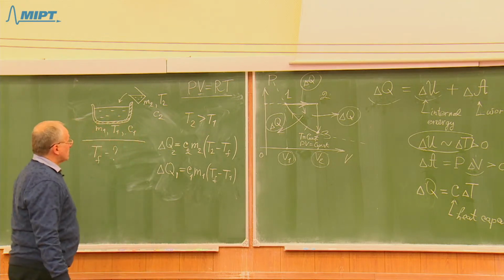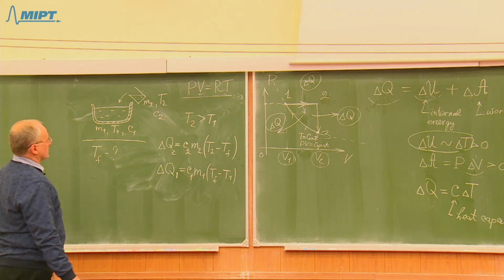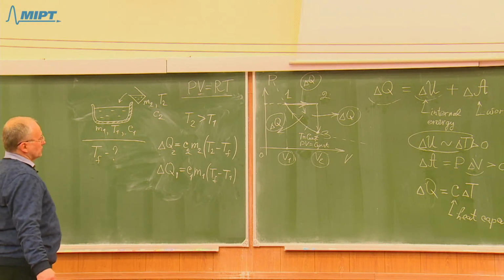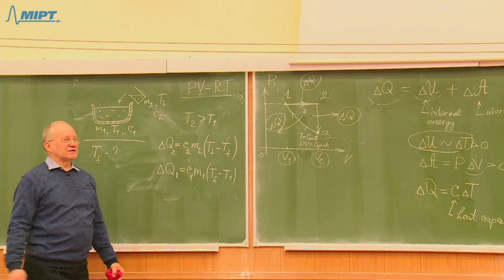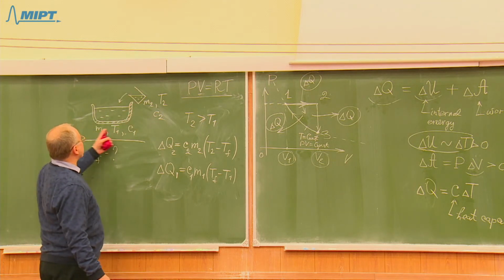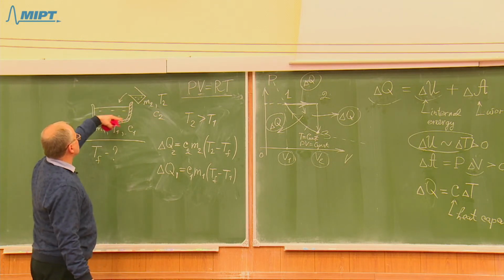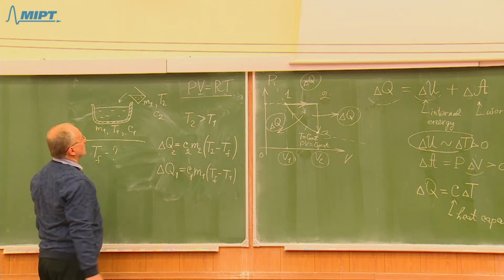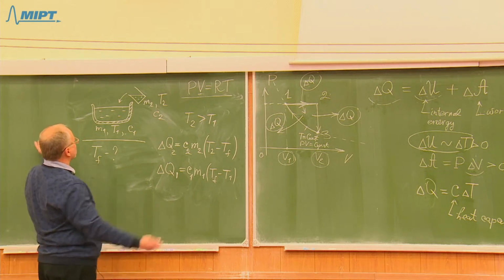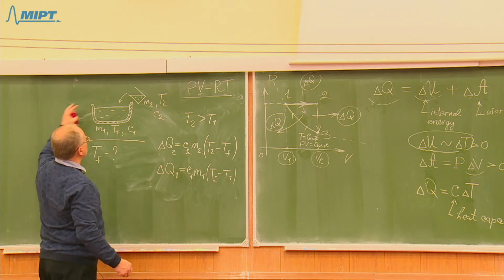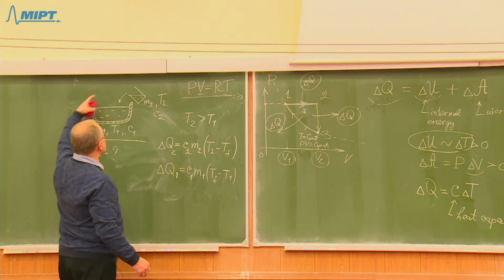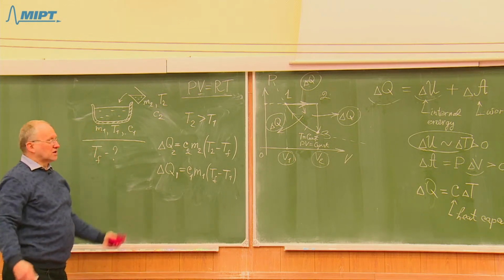The second liquid will have to cool down to some intermediate temperature between these two temperatures. So according to energy balance, the law of conservation of energy says that energy cannot be created and cannot be lost. It's conserved. If this system is placed in such a condition that no energy can flow in from outside bodies and no energy can flow to the outside bodies, so there is no heat exchange between this system of liquids and the outside bodies, then the total heat energy inside this system must remain constant.